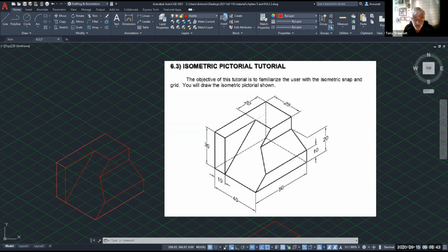Do you want me to redo it on the thing again? I can do that. No, I can follow along. Okay. I come up here and then I just drew a wild isometric line. I just drew it this way. And then remember, I copied this angle and I copied it to here, and then it intersected this, and so I trimmed it, and that gave you this point.